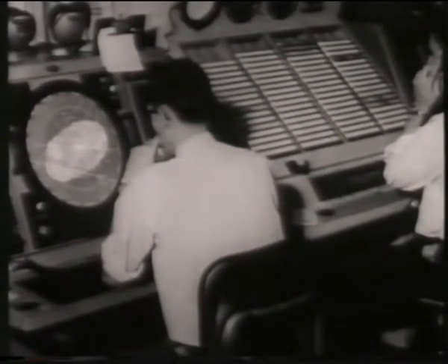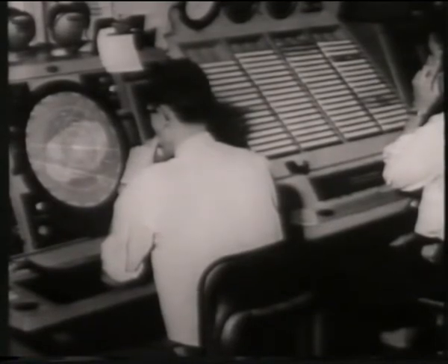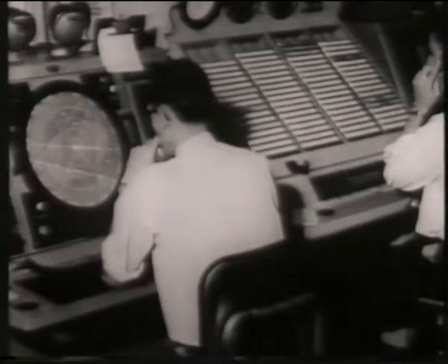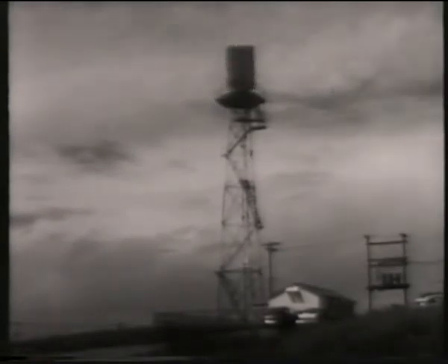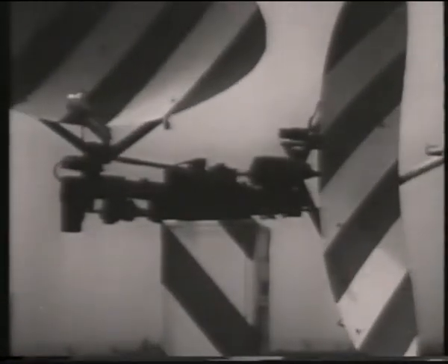A radar picture of an area with an aerodrome at its center may include echoes from surrounding hills, aircraft, and some types of clouds. Depending on what use an observer wishes to make of the picture on the scope, he can adjust controls to regulate the relative brightness of different kinds of echoes. The unwanted echoes are known as clutter. The basic principles underlying the operation of all types of radar are very much the same, and they can be adapted to many uses.